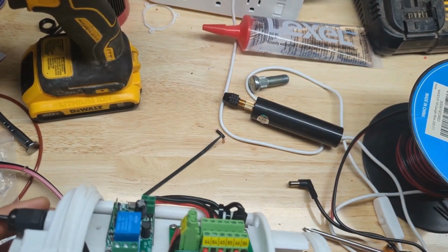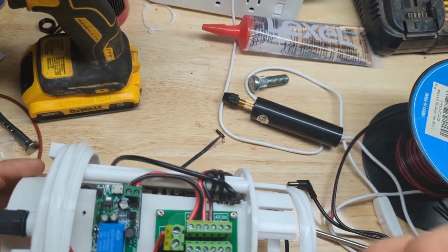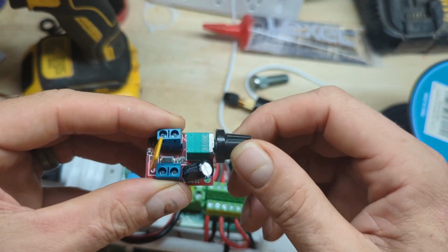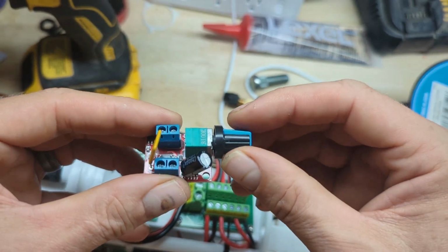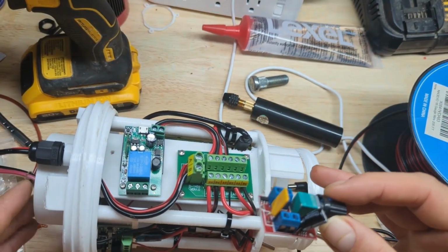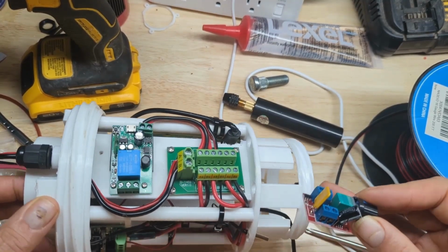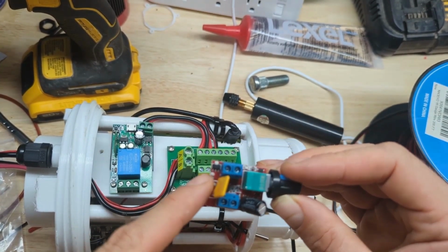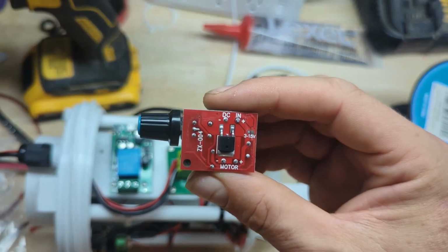Now the last component to hook up, and it will go right here on this A3B3 to get its power, is our PWM controller. So you'll recall this is the device that actually controls how much power we send to our dew ring, because we don't want to have it wide open because we don't need that much power going to the dew ring. The enclosure itself, all the components inside of it will generate its own heat. Just with the Pi running, any of the electronics running will generate heat. So some heat will already be there traveling up to the dome, but this will just add supplemental heat with our dew ring. And if you look at the back of this, these type of applications have many different purposes.